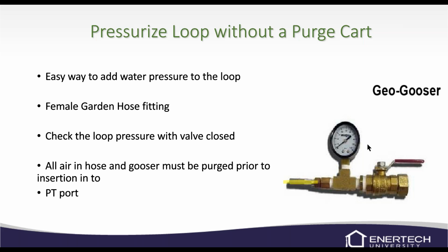It can run lower than that. We just don't want it to run into a negative pressure. Sometimes we see a loop go flat when we're switching from season to season. In the winter, the pipe is cold, so it constricts, and so your pressures are higher. And then in the summer, when that pipe warms up, it tends to want to relax, and you drop pressure. You don't really drop fluid, you just drop pressure.